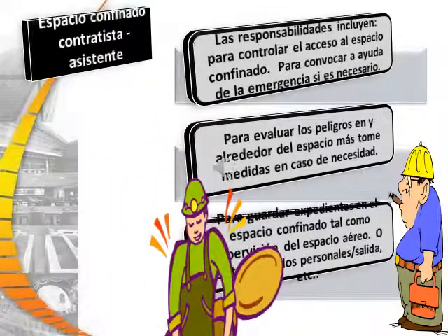Responsibilities include access to the confined space, to summon emergency assistance if needed, to assess the hazards in and around the space, plus take action if necessary, to keep records on the confined space such as air monitoring and personnel entry or exit, etc.